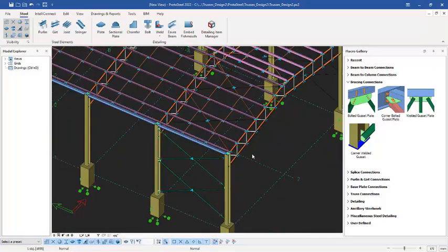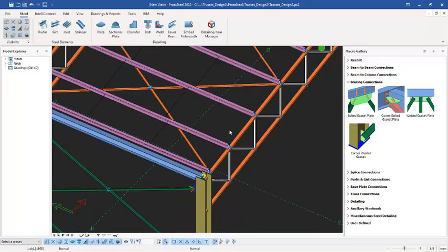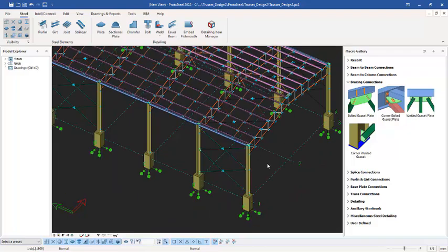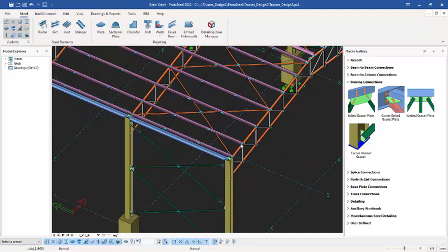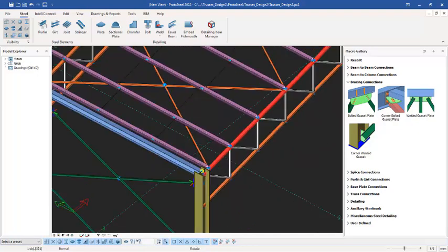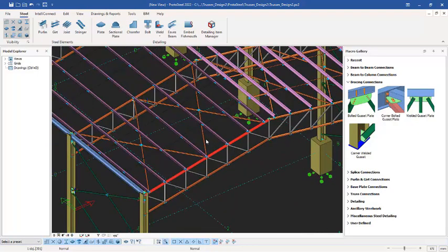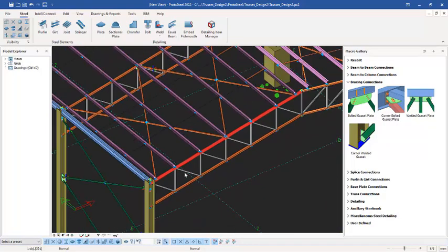So having understood that, let's move to purlin connections. Sometimes there is an option we call interlink connect. In a small structure like this, I would advise you shouldn't use interlink connect. You should just connect them one by one so that you can have neat connections.